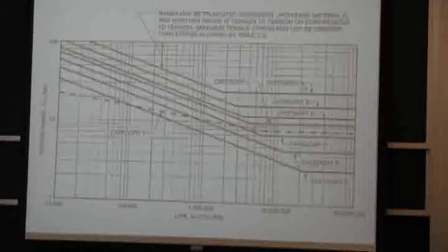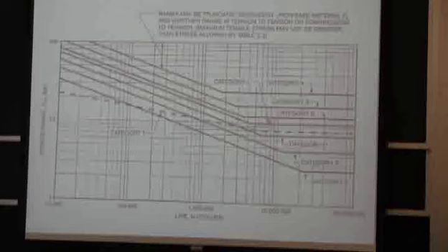And then if you have these welds, like we talked about here, loaded in bending, it keeps going down to about 3 KSI. So it's very limiting. When we think about a material that we formed and it's 40 KSI strong, or whatever we decide to make it, 50 KSI strong, now we're talking very small stresses on those welds.